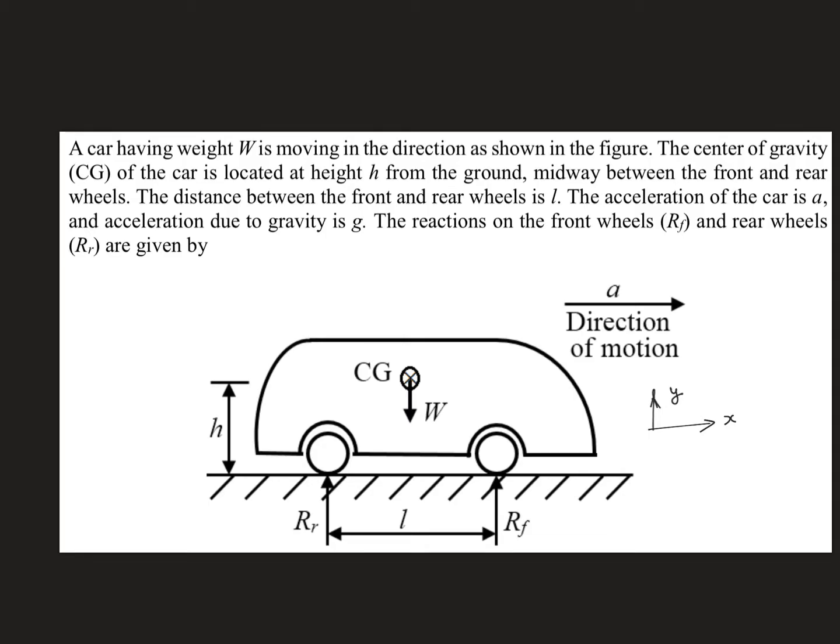Since this is a rigid body, the second assumption comes in. I am assuming my car to be a rigid body. We all know there are deformable components in an automobile, but we are not worried about that for the time being. That's part of an entirely different subject that will be taken care of in solid mechanics. We are looking at rigid body mechanics because what we want to get out of this exercise is the reaction forces. We are not interested in the displacement of the car and all those things.